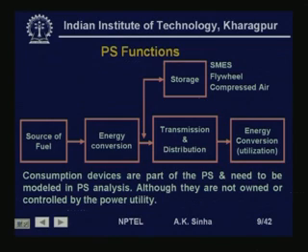Some of the storage devices that are used for large energy storage can be superconducting magnetic energy storage. That is, we have a very large superconducting coil in which we can store this energy as a magnetic energy, and when we need it, we can draw it from that coil. So, this is one of the devices which has been used in a couple of places, but this is again very expensive. Another method which is being tried is flywheels, very huge flywheels, which can store energy in its inertia, and that kinetic energy can be converted into electrical energy later when it is needed.